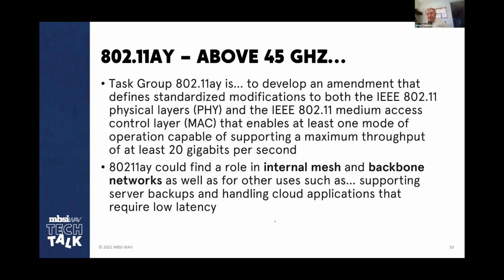So now let's move into our next topic, 802.11ay. It's just coincidental that the AY protocol comes after the AX protocol, but we're going to see it as the protocol that's going to be most useful. It's designed to be above 45 gigahertz, so use that as the floor. So we're talking about 60 gigahertz in this particular case, unlicensed around most of the world.